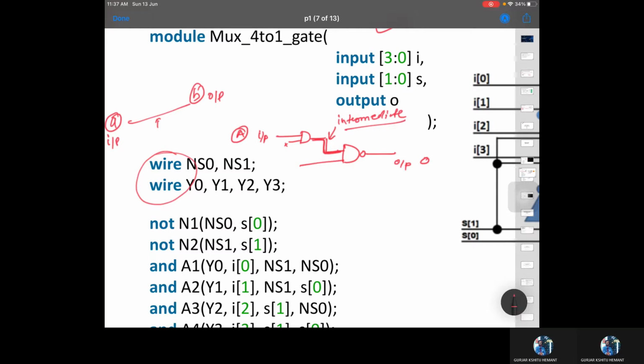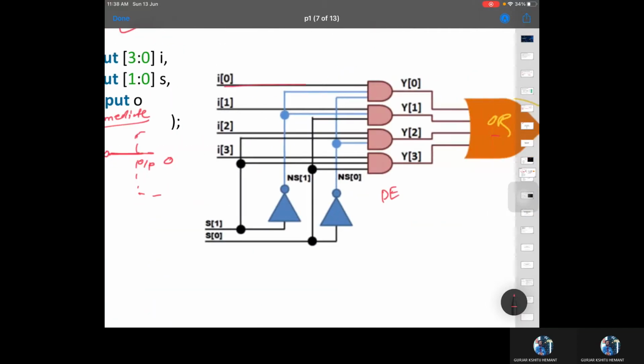This is very important. These things are directly from the input ports, right? Say this is also from some input, this one input. This is directly connected to your output port, output block. Then okay, no need, we have already covered this here. But what about these things? These are intermediate. So you can see here, this is directly connected to the input port, so no need to declare that wire.